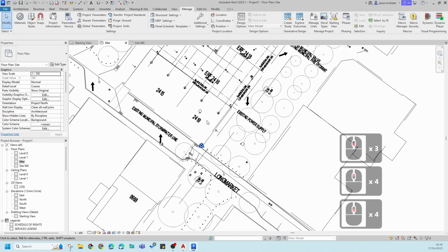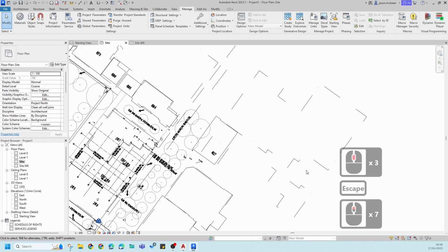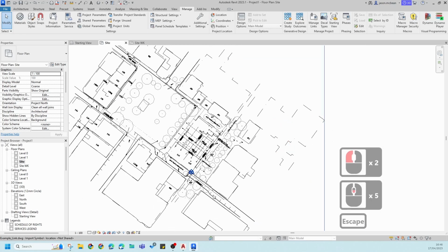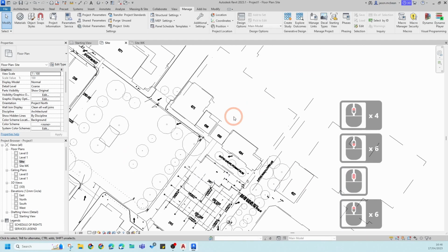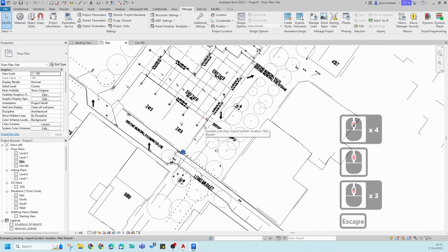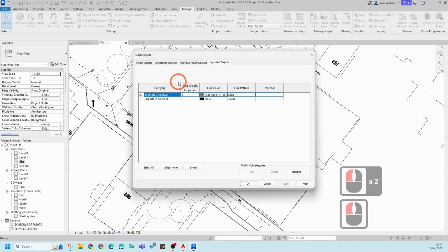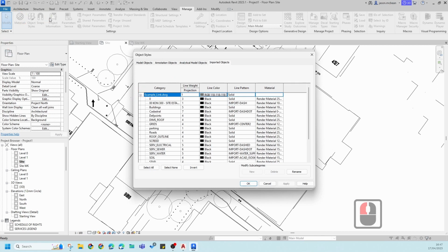Okay, so you can see this has done quite a good job. The next thing I want you to do is, with this imported, you can see there's some dashed lines that we'll need to fix for the side boundaries, but that information we can fix quite easily because I know what layer that is on. So maybe let's just do that for the project quickly, import a category. So here I'm going to go to, remember, object styles. You can access object styles here as well.